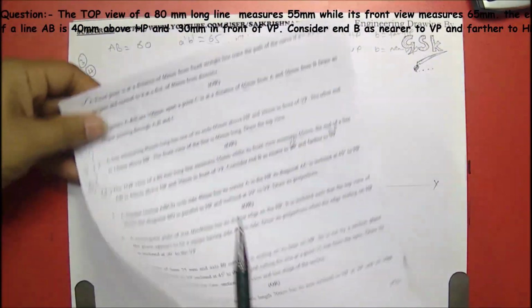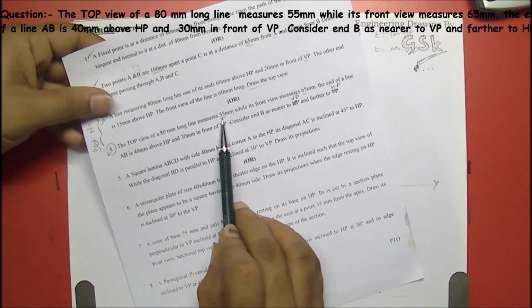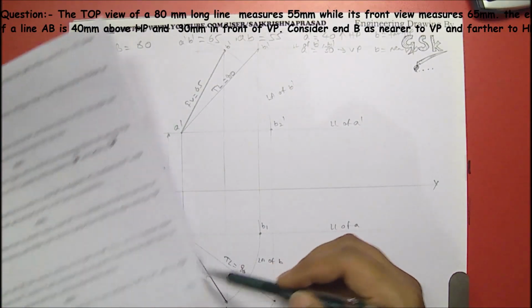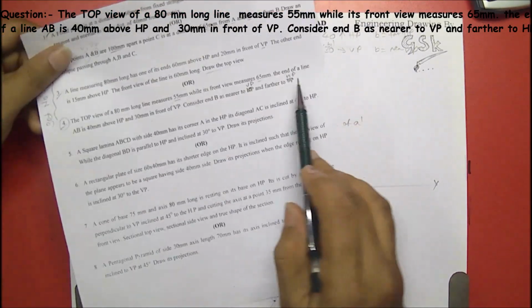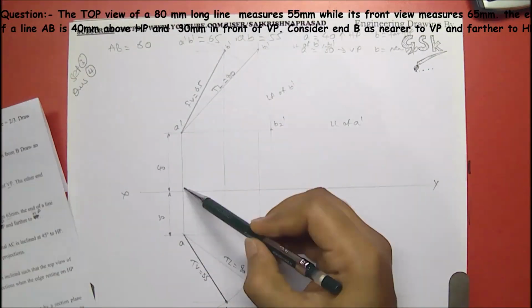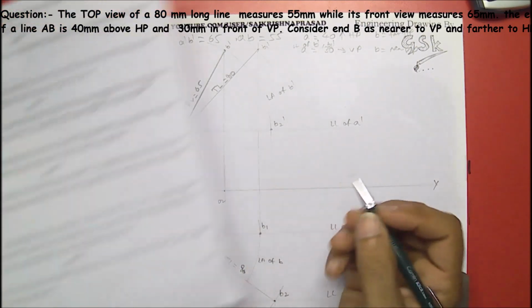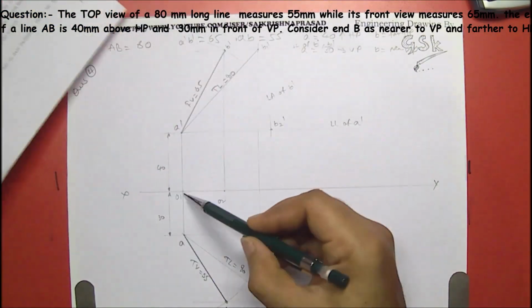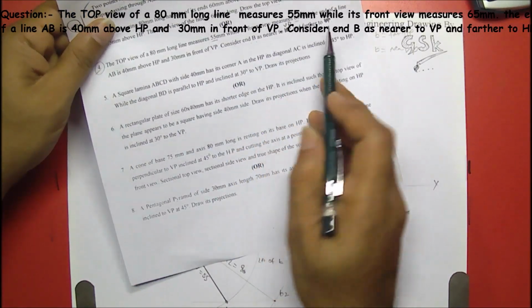Let me read out the question once more. The top view of the line, an 80 mm long line, is 55. See here the 55, and the front view measures 65. See here 65. The end of the line AB is 40 mm above. See here 40 mm above. This is origin 1, this is origin 2, and 30 mm in front, 30 mm in front. Consider B is near to the VP, far from HP.